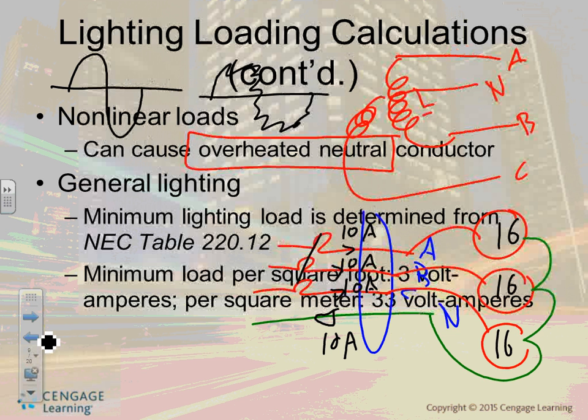Don't worry, gentlemen. We solve the problem by doing the following, right? We have number 12, 4 conductors, okay? Each one of them will be number 12. The neutral will be number 12. 10 amps will not overload the neutral, and you're good to go. That's how they solve the problem. So when you see they overheat the neutral, now there will be situations, guys, especially in the data centers, where the neutral could be overheated if you don't take it into consideration.